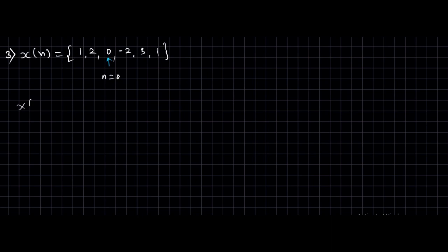So we have X of z. Now we can solve directly. X of z is equal to the summation, this is the first equation of the z transform. So it is n. Now what is the range of n here? It is two samples to the left of 0, so it is minus 2, minus 1, 0, 1, 2 and 3. So this is the length of index n.